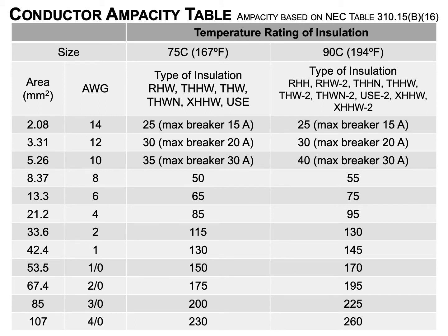We talked about what the letters represent marked on the insulation of the wire. And so here's a chart from the National Electrical Code, which is commonly used in the United States, where I'm talking to you from. And it shows the different ambient temperatures and the insulation rating, and then how much current we can run through that wire with the different insulations on there.